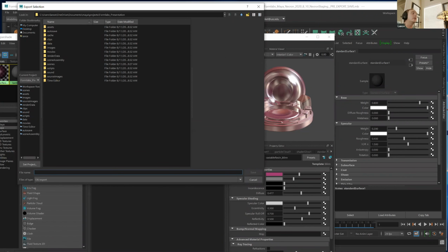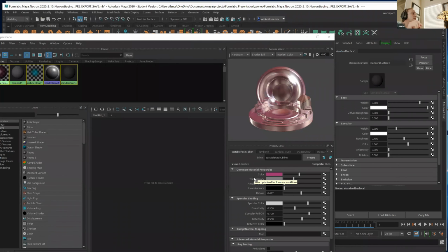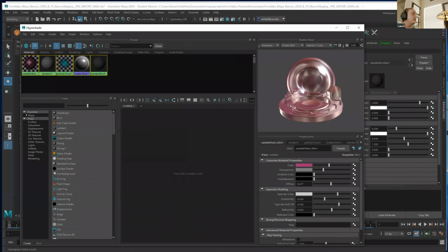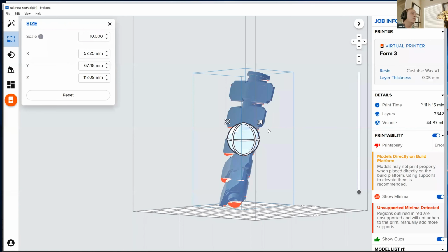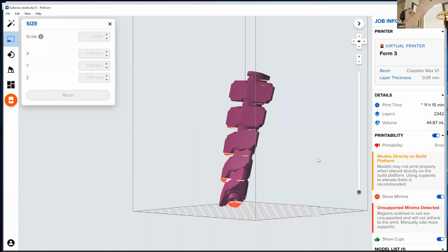So it's very possible. Now, I don't know the exact shading values that they're using within the Preform software, but guaranteed this is something similar to a Blinn or a Phong. It's not a fully photoreflective subsurface scattering shader. So if you just wanted to get that type of shader, I would say approximate it, or even just do a quick RGB sample, which you could do using Photoshop and a screen capture, and then you could start to build these yourself. Be very easy.